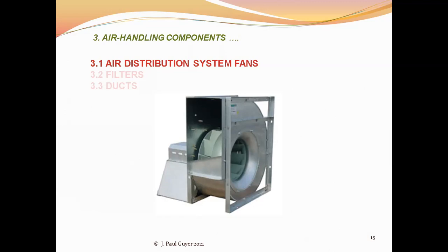And this is for air quality purposes. So entering the fan is a mixture of around 75% return air and around 25% fresh outside air. And then that mixed air is blown across the heat exchanger, the evaporator coil, and is cooled or heated and then pushed by the fan pressure into the occupied space.